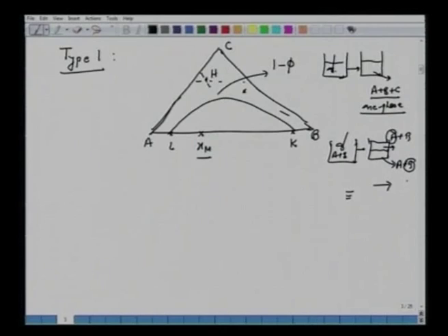With the top product, say vapor, and the bottom product the liquid, both contain A plus B, but in one case A is larger, in another case B is larger. So here we have the same story. If we take this, allow them to settle, now I have L and K represented by this. This one is closer to this apex, so it's rich in A.